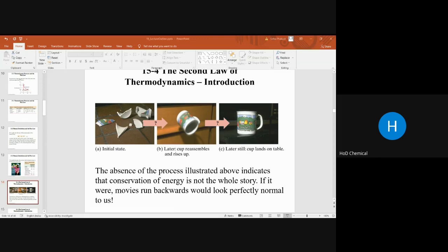Okay, now substituting the COP value as QL divided by W. We already know that QH minus QL is W, so we can also replace W using QH minus QL. So this one is for the refrigerator and air conditioner in practical conditions.